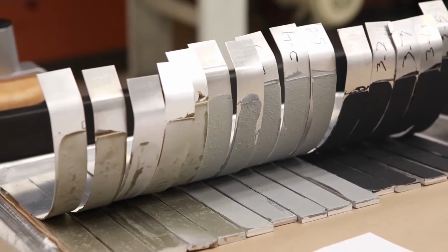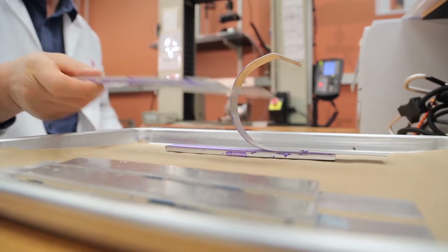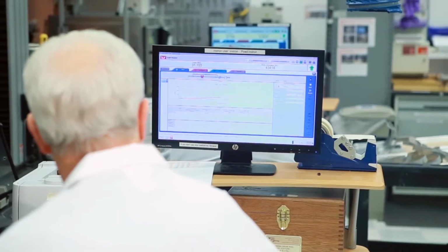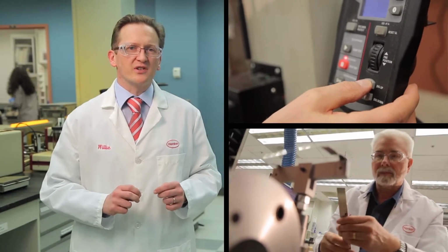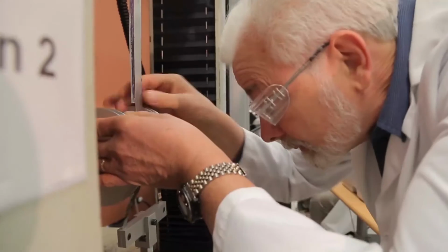All of the applied load is concentrated on the leading edge of the adhesive rather than across the entire bonded area. When designing a bonded assembly, these loads should be avoided as much as possible. One method, called the climbing drum peel test, allows for calculation of an adhesive's peel strength independent of the substrate it is bonded to. A bonded assembly is secured in the climbing drum peel fixture in a mechanical properties tester.